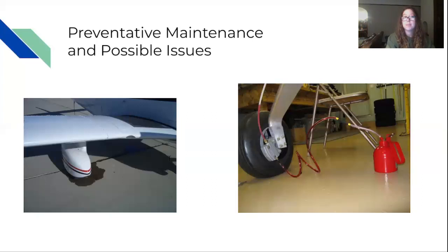Another problem is if the pump is drawing air, which is another possibility, and that means that there is just not enough hydraulic fluid in the system for it to be functioning properly. And this could be caused because of a leak in the tube or a bad seal. And those are the most likely culprits. There are other parts of the pump that can fail, but the most likely cause is going to be low fluid problems. Most problems with the hydraulic system can be avoided as long as the hydraulic fluid is being kept clean and at the levels that the airplane requires.